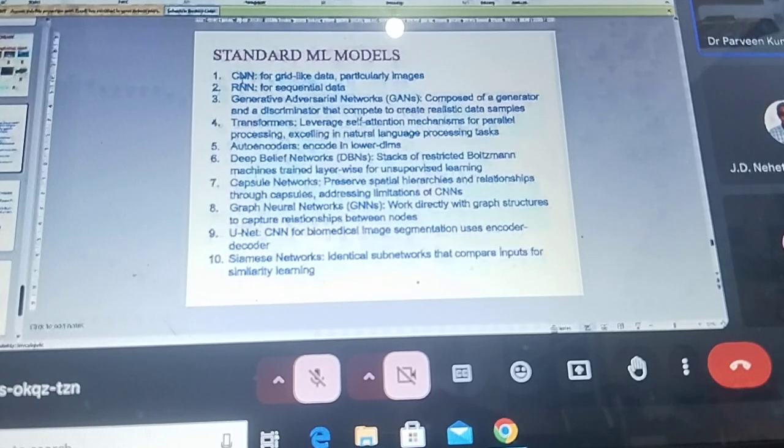Convolution, you know, what is convolution? If we have two signals and you reverse the time axis of one signal, then shift one of the signals, multiply and add, this operation is called convolution.